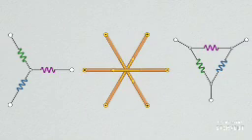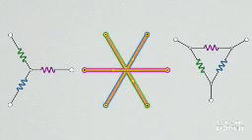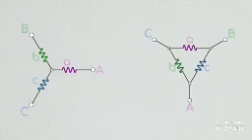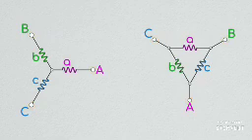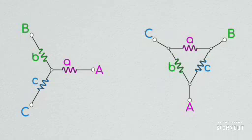Well, there are 2 ways, a Y configuration and a delta configuration. In each of these diagrams, the resistor squiggle denotes a loop of wire which would be aligned with the squiggle. It's worth noting here that the diagram doesn't necessarily match the geometric layout of the coils, but it's an equivalent electrical circuit. In both cases, we would have 3 wires, which I will call nodes, coming out of the circuit. If we connect one to a positive voltage and one to ground, we can now drive a current through our loops.